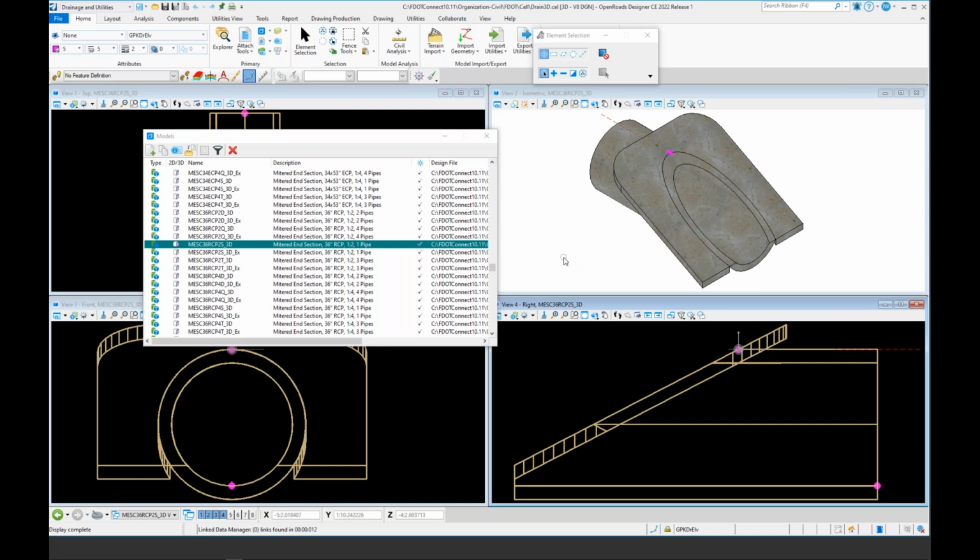So also choosing the size pipe that we're going to be creating a jacket for allows me to model the jacket around an actual pipe, so that I don't have to hand calculate wall thickness and all this other stuff that's needed for the point placement, the connection region placement, and all these other factors that come in while we're doing this modification.